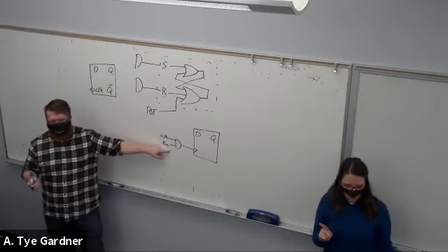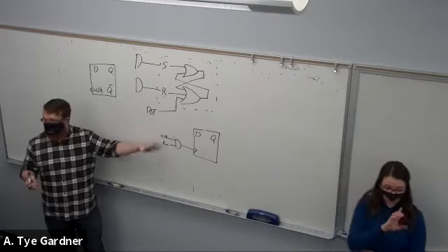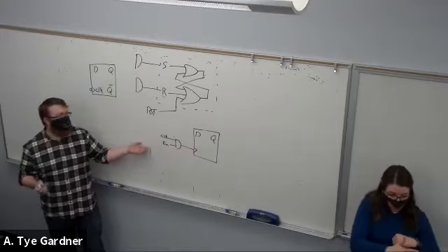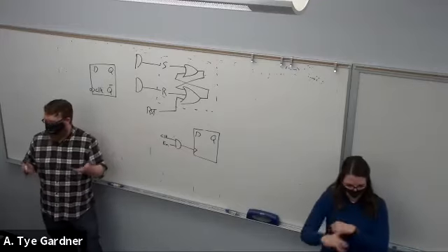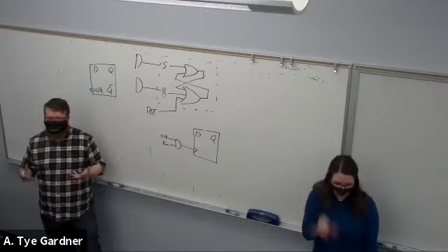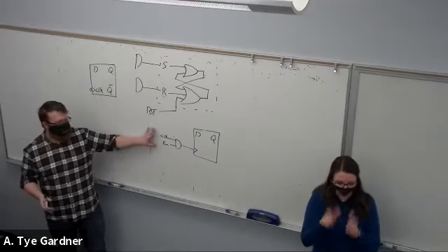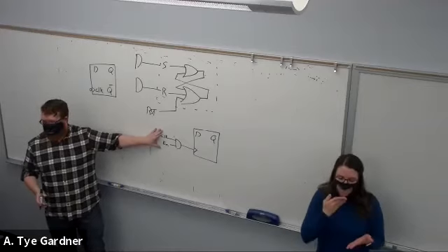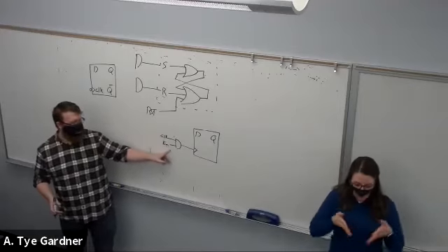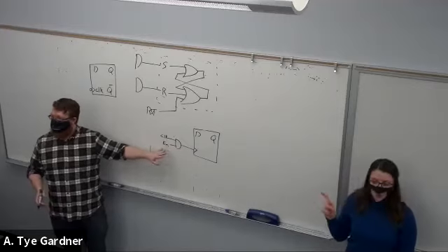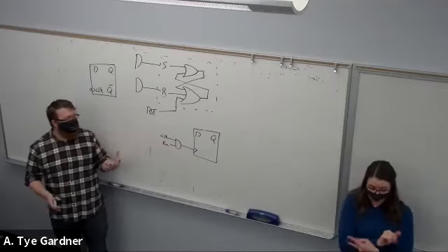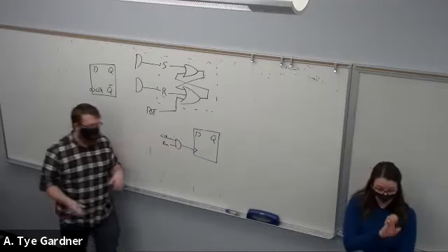If enable dropped early, the clock period would end early, right? So both can generate clocks. We don't really like that. It can cause issues, especially in what we call high-speed designs. This is a bad way of doing this. Know that it exists because we like AND gates for enables, but in this case, it doesn't work. So we need a way to avoid this problem.